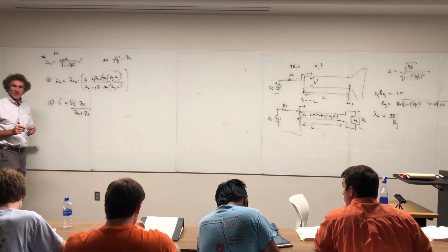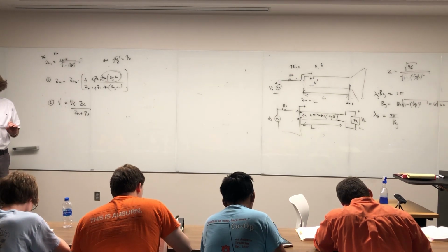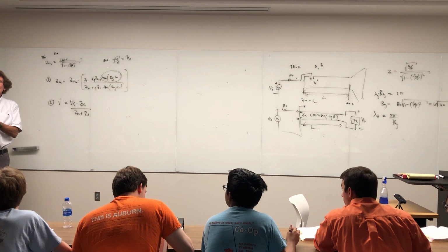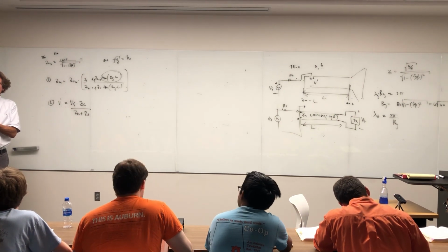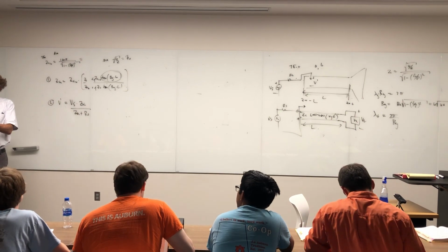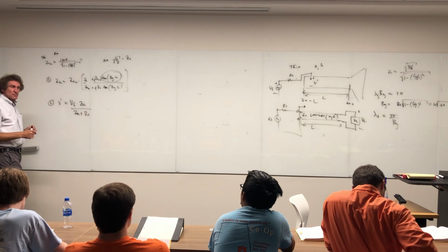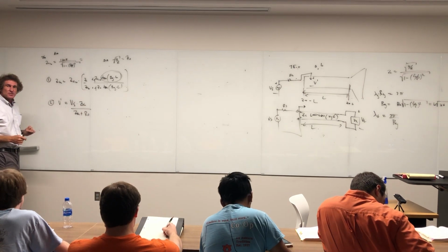Can y'all appreciate that? Remember doing this in the transmission line problems? Now we get the voltage just inside the transmission line, right? With a waveguide, you get a voltage from the very top of the waveguide, the middle of it, to the very bottom, middle of the guide. And that is going to be a voltage. All right? And it's measurable too. So that's this voltage. Now that's the voltage just inside, right?